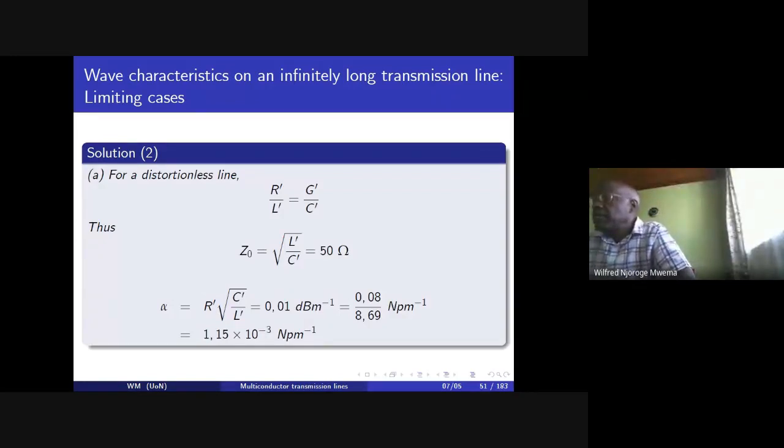So that's where you get the 8.69, or 8.686 dB per neper, and you divide therefore by the value of the characteristic impedance, okay, that is the attenuation. We divide that by the value of the dB per neper, so to speak. So this, I think, is a problem. It should be unity, not 0.8. I think that's an error.